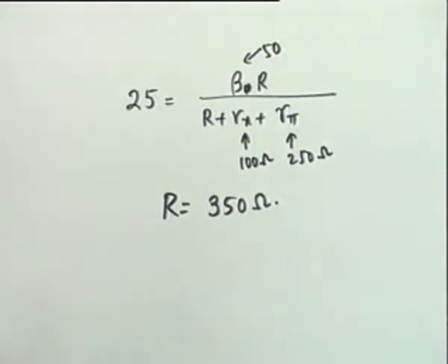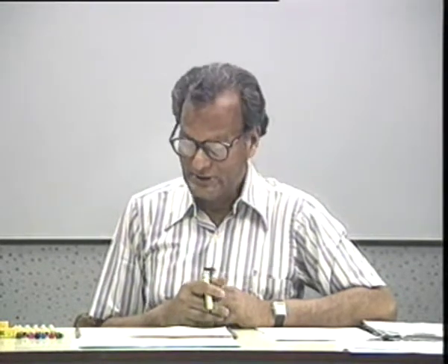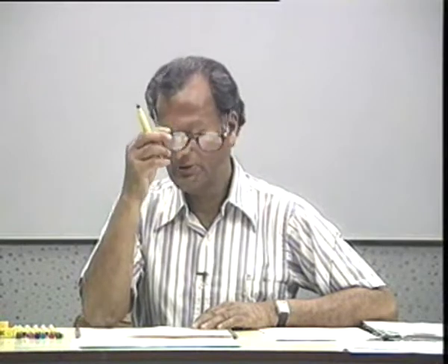To find the inductance L, yes. So this capital R is not a discrete element, it's a part of the inductor. That is correct. So while designing the inductor, we are assuming that this is the maximum resistance it can offer. It should not get more than this. Now, in practice, suppose the coil can be made with less value of inductance, then you can either redesign the circuit.